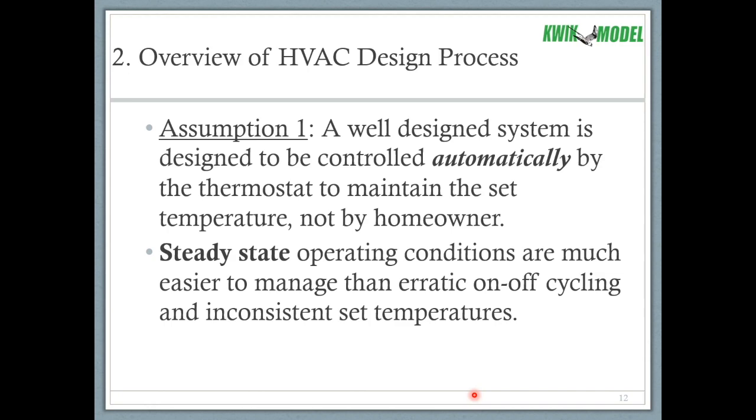The outdoor temperature is rising to its highest point and then dropping down to its lowest point. It's going up and down, but it's doing that very slowly. And the indoor temperatures are staying very constant. You might have unoccupied times and occupied times, so there might be a setup and a setback temperature, but other than that, the temperature is staying constant. We are designing to those conditions. If the homeowner is not willing to operate a house at those conditions, then it's a completely different situation and it's just not going to work. So a big part of HVAC design is educating people who are going to operate those systems.